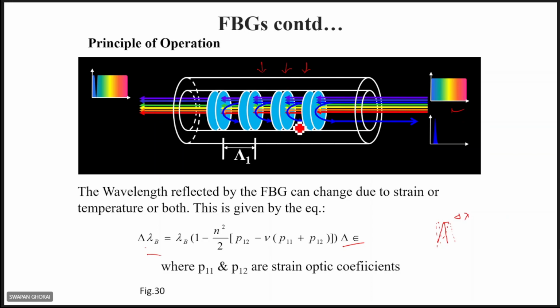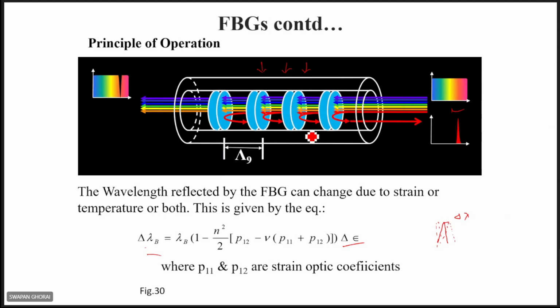So now it is quite clear how the Bragg grating operates. Here it is red. By changing this periodicity, the Bragg condition can be changed, so accordingly the reflection of light will be different. This is the input source spectrum, but after the grating the reflection spectrum will be only these, and the transmission spectrum will be these.